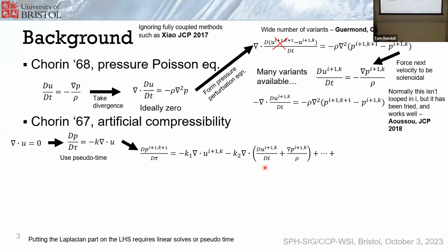And the consequence is that you start to see Laplacian type contributions appearing in terms of pressure, and they do help to suppress noise, which you would otherwise be seeing in your pressure field. And it's driving it to a solution of the momentum equation, which is physically what you want. So within a time step, you solve that, and then you arrive at your satisfactory pressure field.